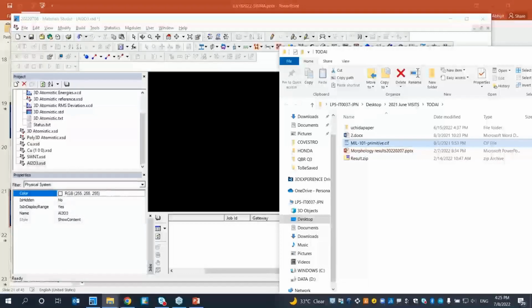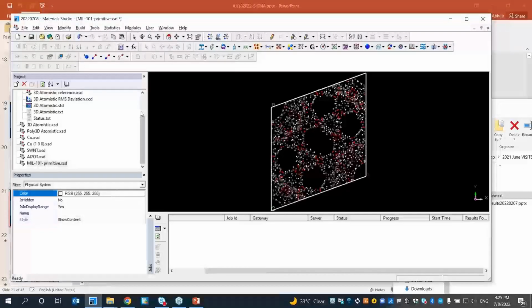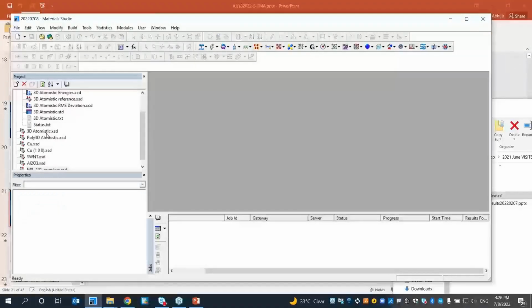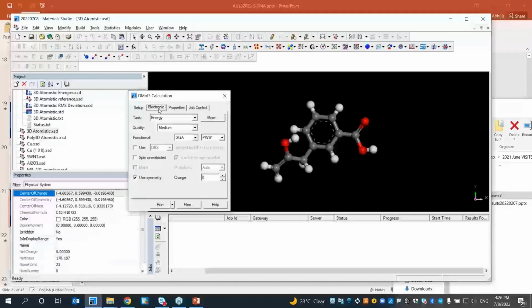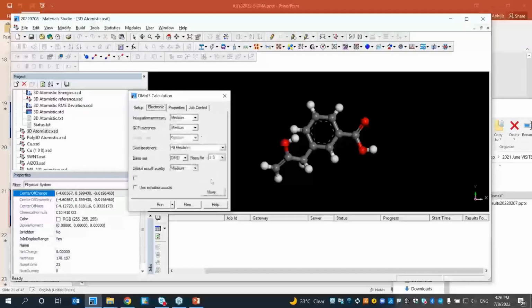You can then choose what method I will be using, right? What I wanted to do. So these are all from the interface. You can calculate energy, geometry optimization, transition state if there are reactions you're looking into. There are LDA, GGA, meta GGA, hybrid, different functionals you can choose. You can choose if spin is required, the charge. You can choose the electronic properties, the basis functions, and you can make manual changes once you have the input file, but it's all from the interface, right?